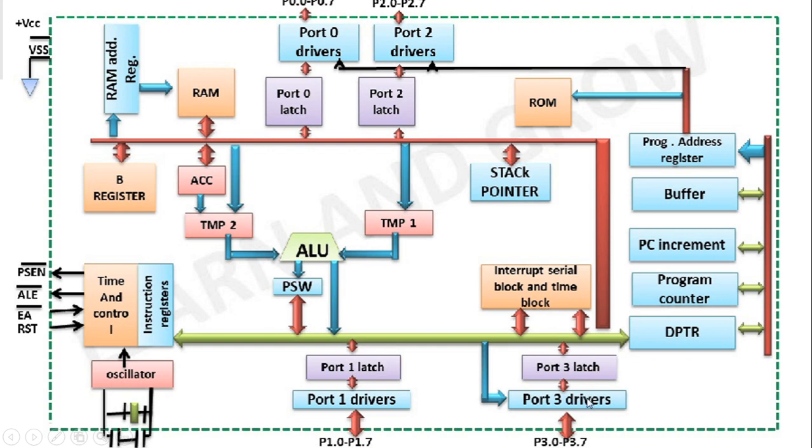And used for transferring timer information, and also for transferring interrupt request and interrupt related information. So port 3 has different functionality. It can transfer IO data, it can transfer serial mode of data transfer, it can transfer timer information, and also can transfer interrupt related information, right?